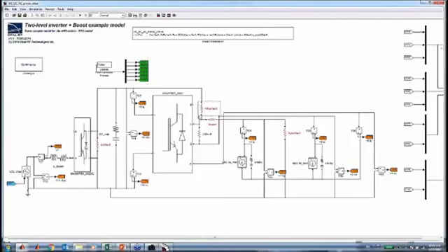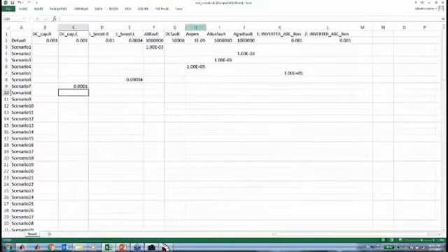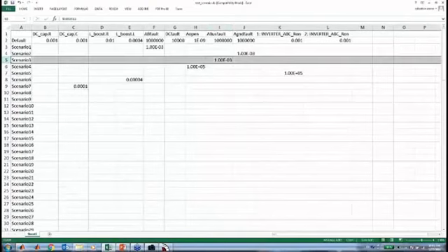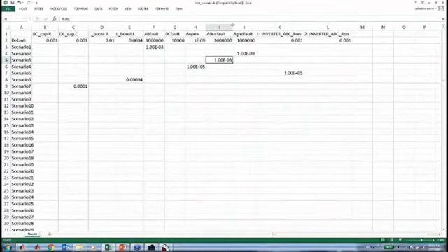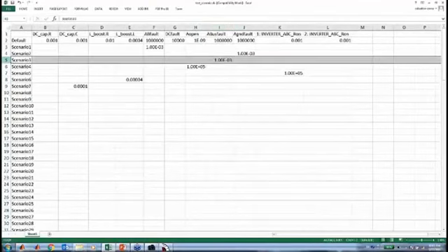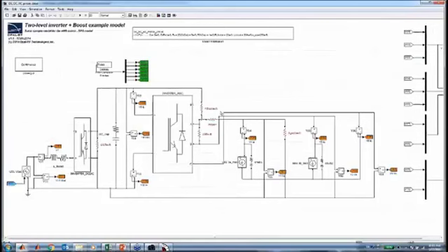So here it's for the A bus fault. This is the A net, and I place a resistor of 1 megaohm here. When I apply the fault, so the A bus fault is here, I'm going to put the resistor value to a very small value, so 1 milliohm. This way, it's very easy to apply any fault you want, because you can place any resistor you want everywhere in the circuit. This is one feature, very interesting if you want to do fault insertion at the model level.